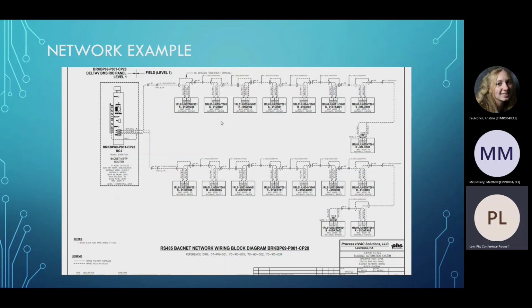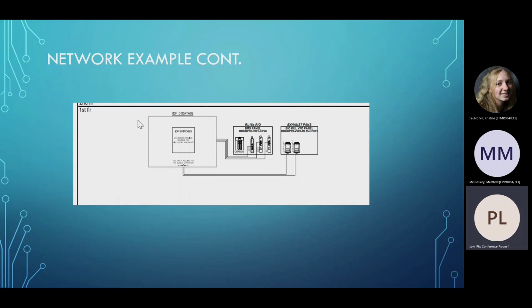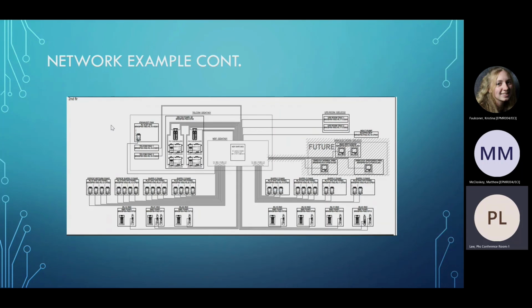All of them are daisy chained together, associated with this part, and this part converts to Ethernet. The Ethernet comes out, goes into the switch, comes out, and talks to the Rio. Then the Rios go to these switches here, which is still BACnet all the way through, just Cat6 into the main switch hub here. Then it comes out as BACnet and goes into the Jace.